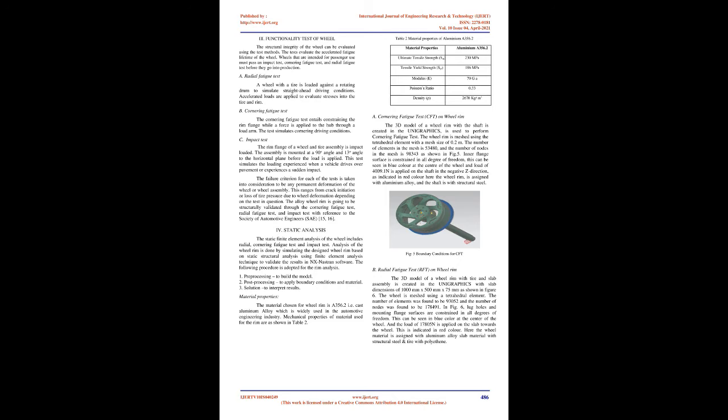3. Functionality test of wheel. The structural integrity of the wheel can be evaluated using test methods. The tests evaluate the accelerated fatigue lifetime of the wheel. Wheels that are intended for passenger use must pass an impact test, cornering fatigue test, and radial fatigue test before they go into production.